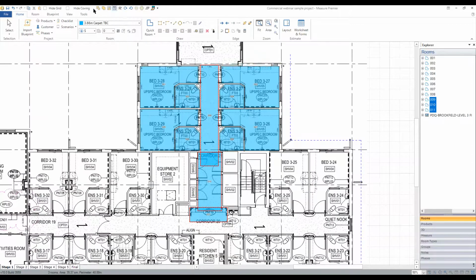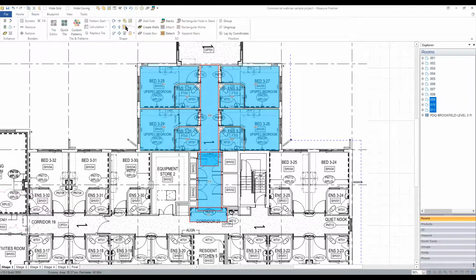And then now I've added a number of tools actually up here to my quick access toolbar. But the tool I'm looking for is this one right here. So it's a join tool. And if you right-click on any of these tools, you will have an Add to Quick Access toolbar option. So that will add it up here. So on big commercial projects like this, there's probably maybe one or two tools that you're using all the time. So that would possibly make sense to add up there.